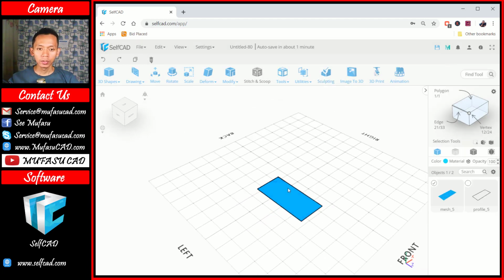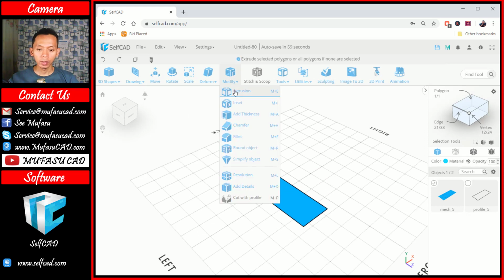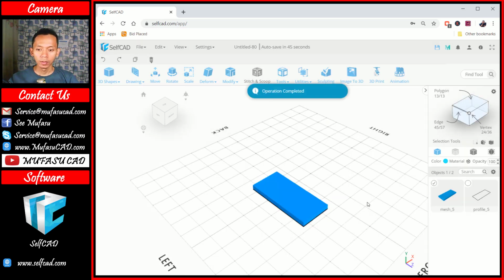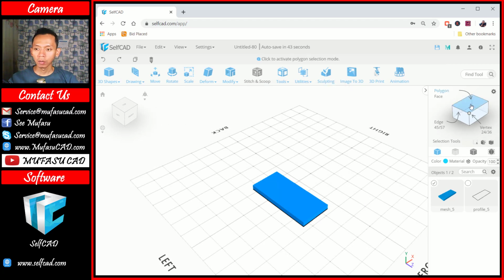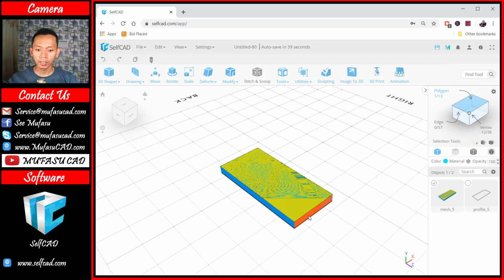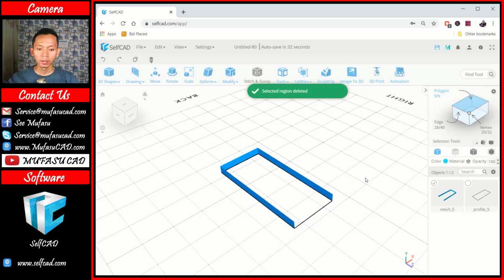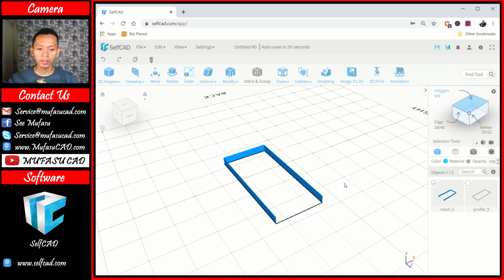And then you can use the extrusion command to extrude these objects. And I will change the amount in here into 15. You also can uncheck this individual option. Next we can click OK. I will click this polygon option and then you can select this face and then you also can select in here. You can press the delete button to delete these two faces. You can click yes. The next we can convert this surface into 3D models.